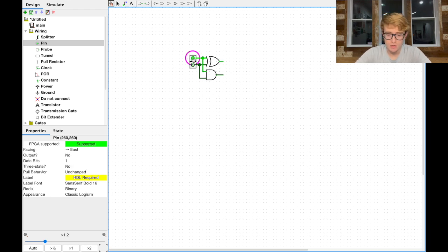You can see I clicked this, so that's a logic level 1 now, and that bright green means logic level 1. So what am I doing? I'm adding 1 and 0, because remember this is my first input, this is my second input, this is my sum, and this is my carry for the half adder. So this is 1 plus 0, which is a sum of 1, carry of 0. Same thing for 0 plus 1. And then I can do 1 plus 1, which is a sum of 0 and a carry of 1.